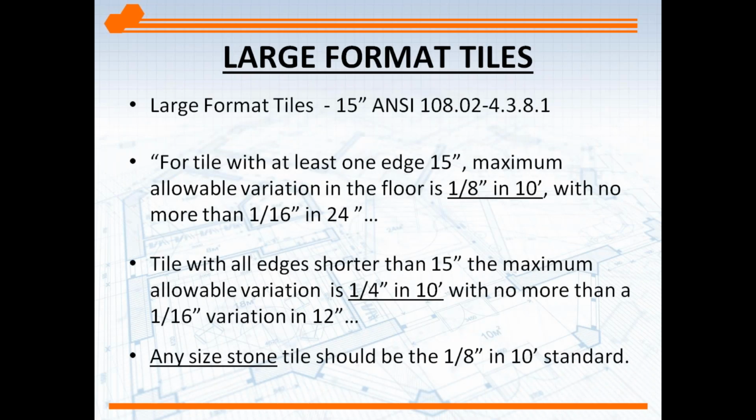Okay, large format tile, as we said, 15 inches. For tile with at least one edge 15 inches or larger, the allowable variation in a floor is 1/8 in 10. So in a floor, you could have 1/8 a dip or a bump above your finished grade. 1/8 above or below is acceptable in any 10-foot area. If it's deeper or higher than that, then the floor has to be treated with either maybe grinding for high bumps or filling for low bumps. And also no more than a 16th in 24 inches. Now that's for large format tile, 15 inches or larger.